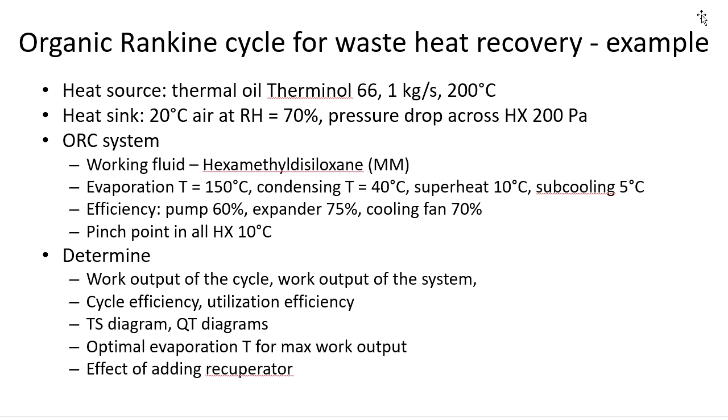So let's go to our calculation example, which will be a Rankine cycle in an application of waste heat recovery. We will have given the heat source, which is specified here as thermal oil of type Therminol 66, with given mass flow rate and temperature. Also we have the heat sink, which is air at given relative humidity and given pressure drop across the heat exchangers, so that some auxiliary fan will be needed for the heat rejection.